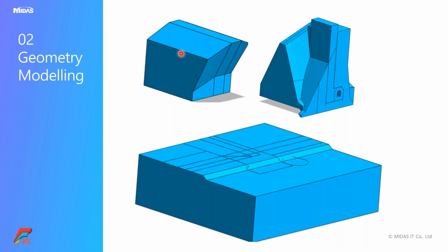The reason for modeling the backfill here, which is in interaction with the abutment, is to consider the effect of backfill due to earthquake load. Whenever the earthquake wave passes from the base to the surface, there will be some amplification upwards, and that earthquake has both positive and negative amplitude.